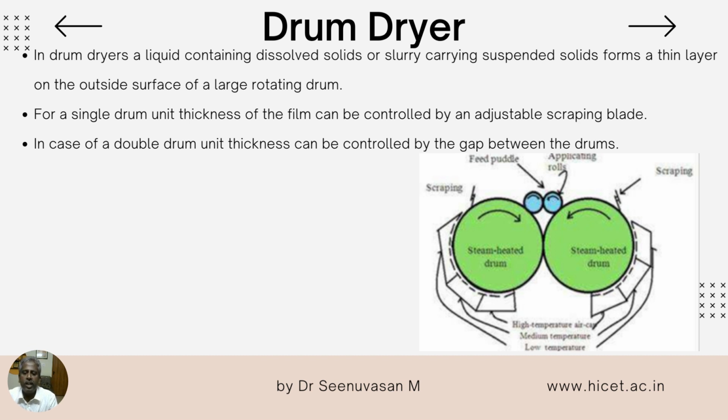The drum is rotated continuously by a gear driven by a pinion that receives its motion through a belt or a chain or a reduction gear. The speed of the drum may be regulated by a variable speed drive to adapt the speed to any slight variation in the feed quality. The speed of the drum is regulated depending upon the nature of the material, whether the material is wet or dry. The speed should be decreased or increased accordingly.